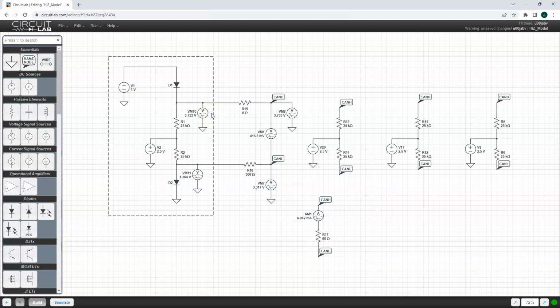I have increased the voltage on CAN high. And the reason that I've done that for just a small amount is because I've got a lot less current that's flowing through here now. That means this diode is conducting a lot less, or whatever electronics I have here, and in so doing, it's dropping less, and so I'm getting closer to this 5 volts. That's the reason the CAN high increases.